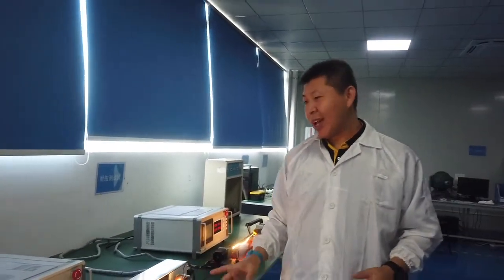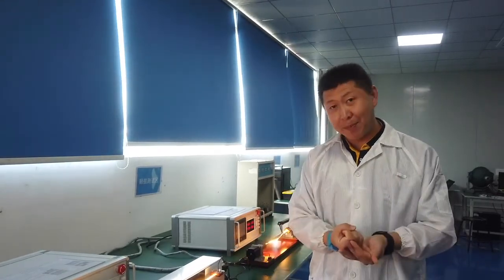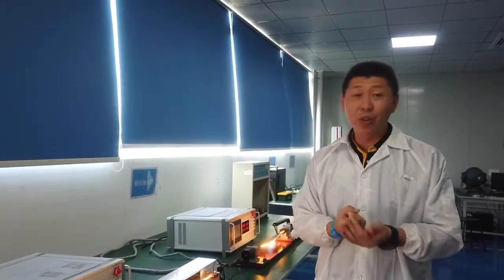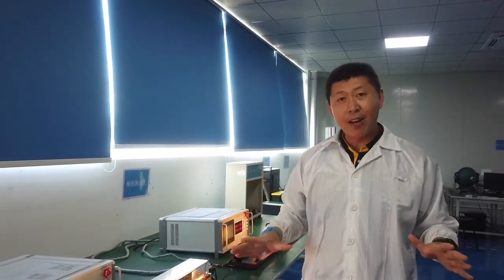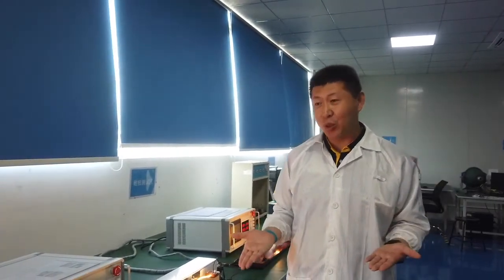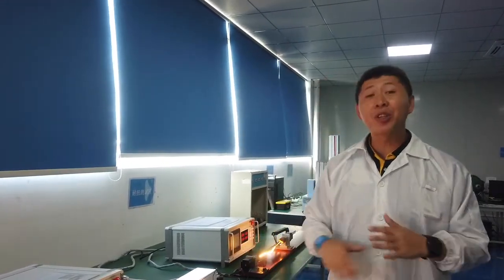After the test cycle finishes, we will first test the appearance to see if the string, glue, and LEDs look alright or not, and then we check the soldering, whether there is an LED or string failure in lighting, and test the parameters again to see whether they changed before and after the test, to decide whether the reliability test is okay or not, pass or not.